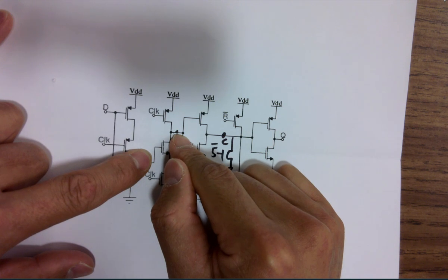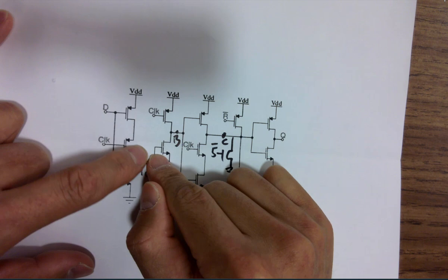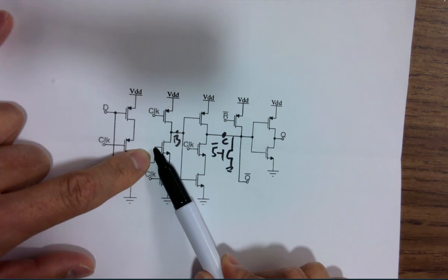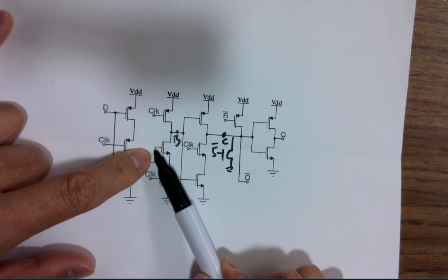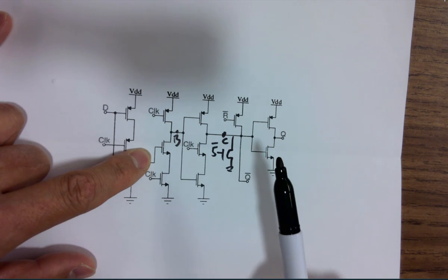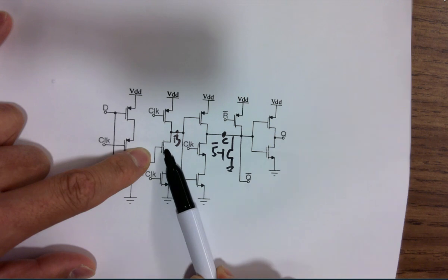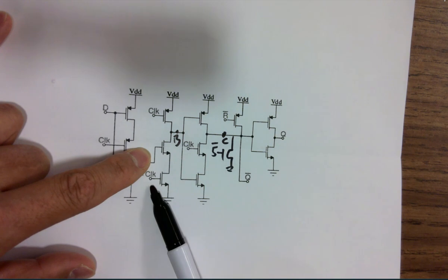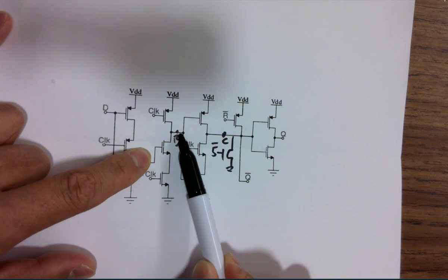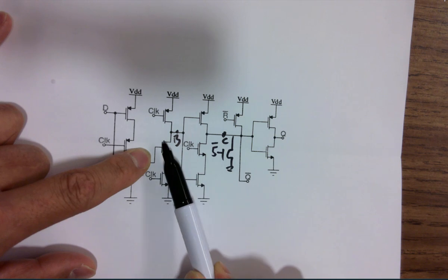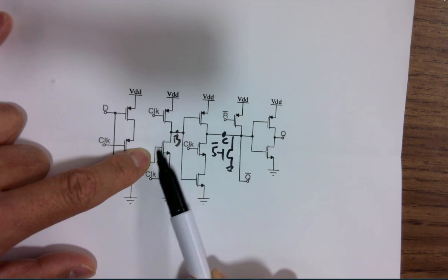If I have a 1, for example D naught here, now it's not 0 anymore. It's a 1. What's going to happen? If this guy's a 1, it's going to activate the NMOS, so this will be on, right? And this is on because the rising edge is on. Both are on. What's going to happen to node B? It becomes 0. It's being pulled down to 0. So if I have a 1, you get a 0. If I get a 0, I get a 1, right?